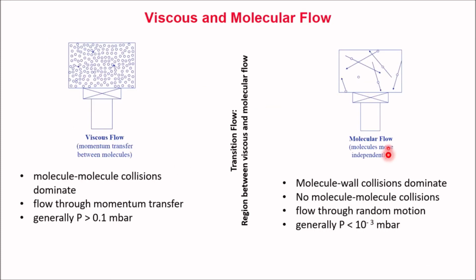This slide is to give you an idea what we mean by molecular beams. Different gas flow patterns are typically observed when a vacuum system is evacuated by a pump. As the pressure in the system decreases from atmosphere to very low pressures, gas flow patterns change from viscous flow to molecular flow. In viscous flow, gas flow is limited by the viscosity.